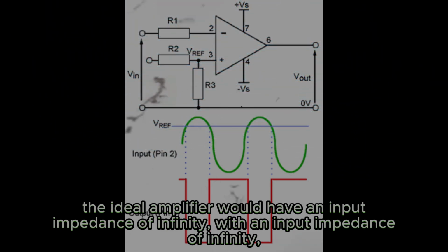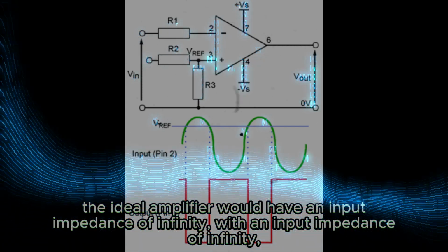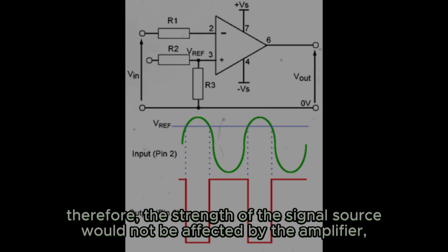The ideal amplifier would have an input impedance of infinity. With an input impedance of infinity, the amplifier would not drain power from the signal source. Therefore, the strength of the signal source would not be affected by the amplifier.